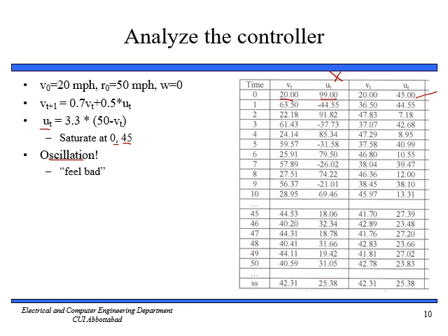Without the saturation, in the next step we have a speed of 63.50 and a control input of minus 44, whereas with saturation we have a next speed of 36.5 and a control input of 44.5. After steady state, this is 42.31 and this is 42.31, so there's not much difference between the steady state speeds, though we want our speed to be near 50 miles per hour.